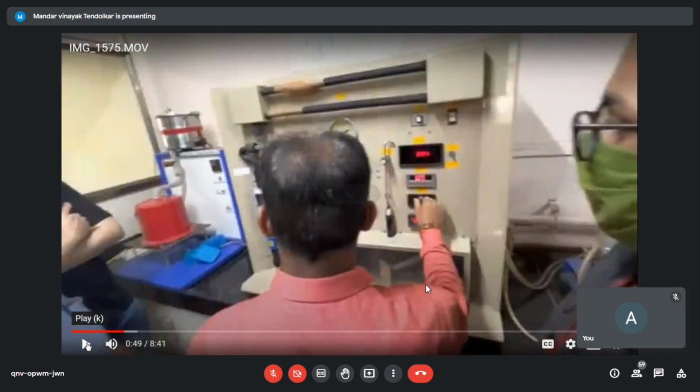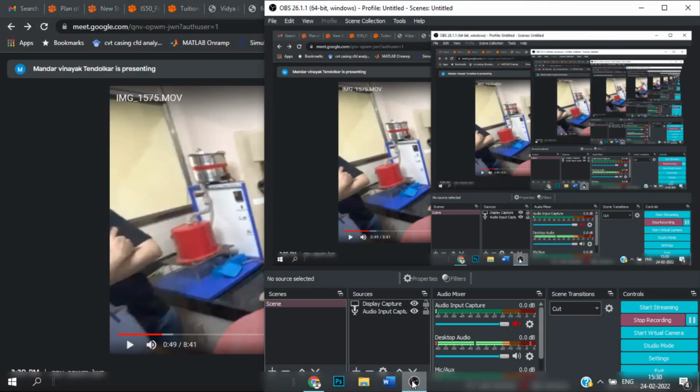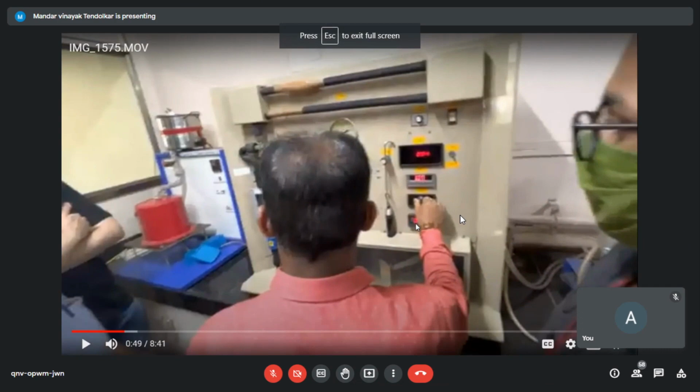So you have just started the unit. So you can read over here certain evaporator load. Then over here, different temperatures. What he is holding with the hands is a knob, so that I can get the reading of T1, T2, T3, T4, etc. Okay, different temperatures. So he rotates the knob, and accordingly you will get the temperatures. This is the load, that means wattage, and here at the bottommost part it is the RPM for the motor. Okay, so wattage, temperature, and motor speed.